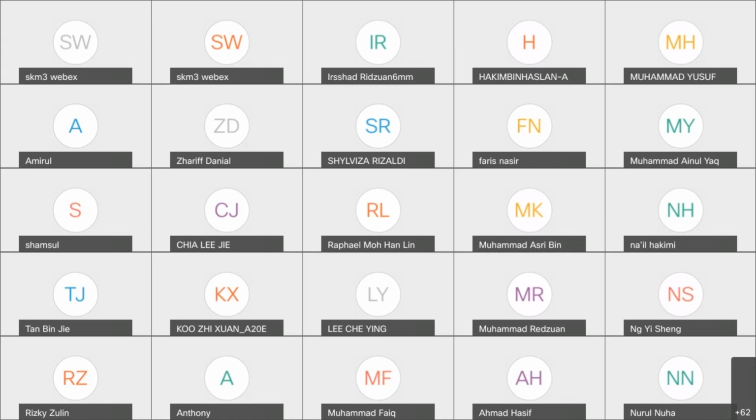Shear for the upper plate, shear 1, is like we did, then we get 0.0764, and for the below plate, shear 2, we get 0.0394. And then we add together the shear from plate 1 and plate 2, we get the total shear. Then we use that total shear to get the force. That's it. Yes, that's perfect.